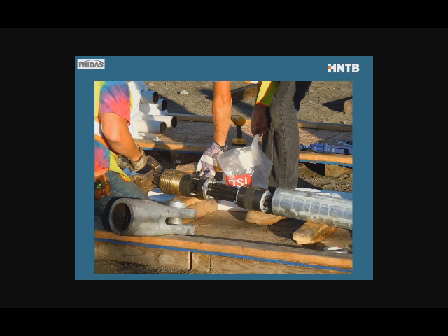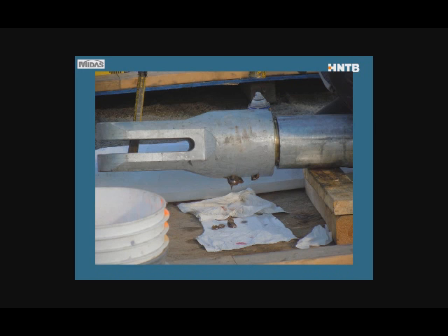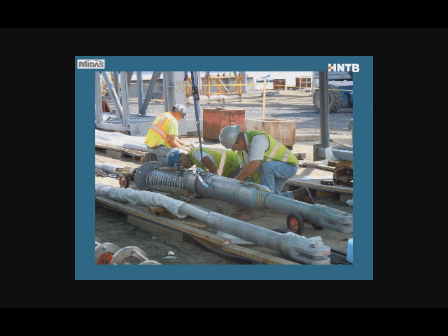They're there to seal the system against moisture intrusion and to hold the pipe in place. So they can squeeze the whole. This is a neoprene collar, and they squeeze the neoprene collars together, and that expands the system, that ensures water tightness and proper seating. In the foreground, you can see a machined, or actually a cast piece, pin piece, and that will be threaded on the thread of the anchor plate. So in this next picture, you can see it's been threaded on and filled with a corrosion inhibiting grease.